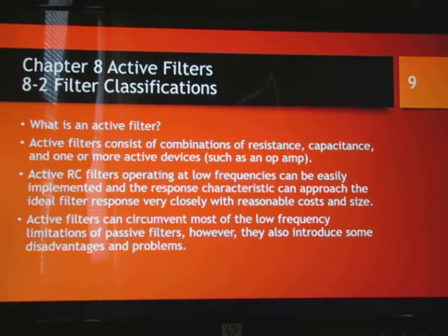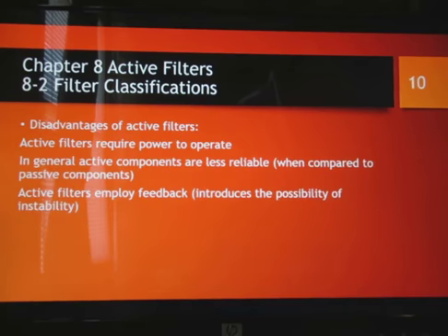Active filters are considered generally to be used at low frequencies, with a limit maybe up to 100 kilohertz. However, experience is the best teacher on the type of filter to use, either active or passive. Any type of active device requires consistent, clean power to maintain the system.